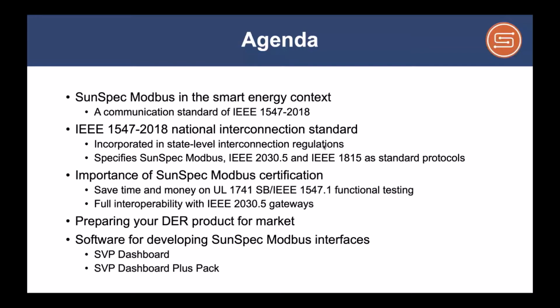That is the default utility to system communication standard used in California, and quite commonly this data communication network terminates at a gateway device that converts 2030.5 to SunSpec Modbus. So certification will guarantee that you have the end-to-end communication that you need to make the system operate well and work well for you in a profitable way.